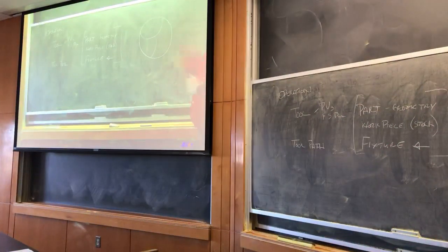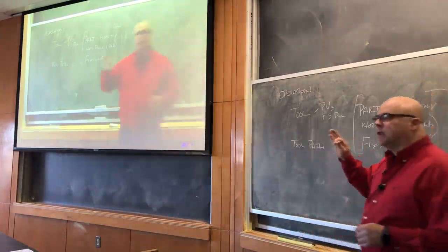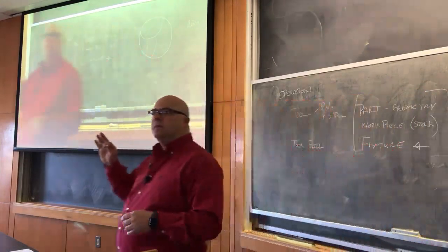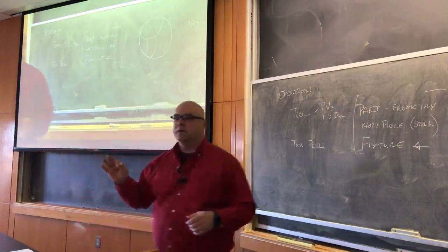If we're looking at this, what's the surface speed here? RPM times diameter times pi divided by 12. If the units work out, that's what it is. Did you guys know that engineering math is just a bunch of word problems? Cancel the units.